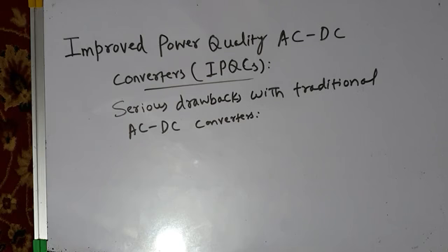It is distorted current, and this distorted current results in distortion in the voltage at the point of common coupling. And you have also seen through the simulations that these converters draw large reactive powers, especially at large delay angle or large firing angle values, right?